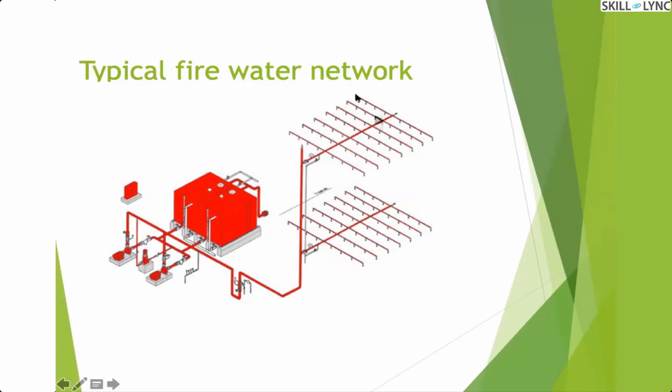But when your flow is happening up till this point, then your pressure at this point will also be different. So when you have to do a network analysis, in that case also simulation is required. When you have such networks, you will calculate the hydraulics at each location, and by solving the equations, you can determine the pressure at each point.